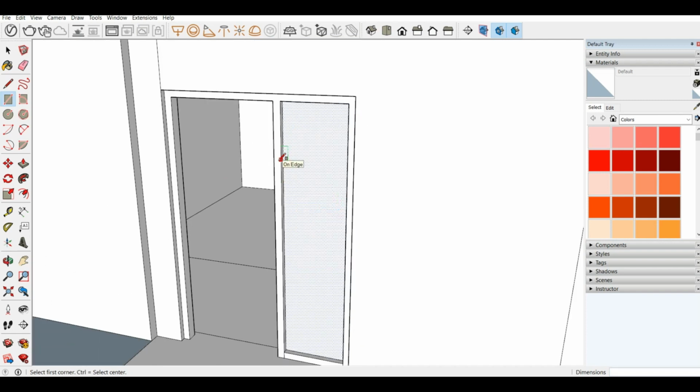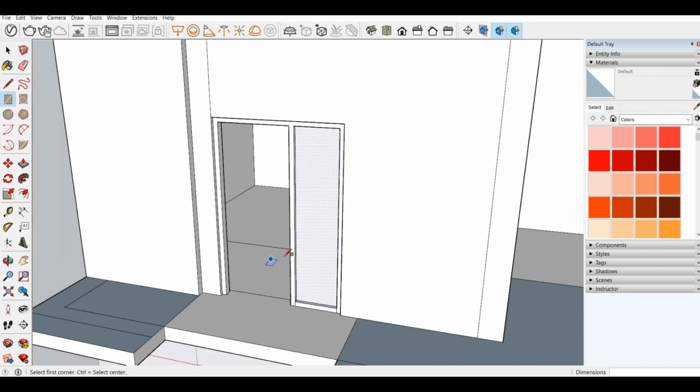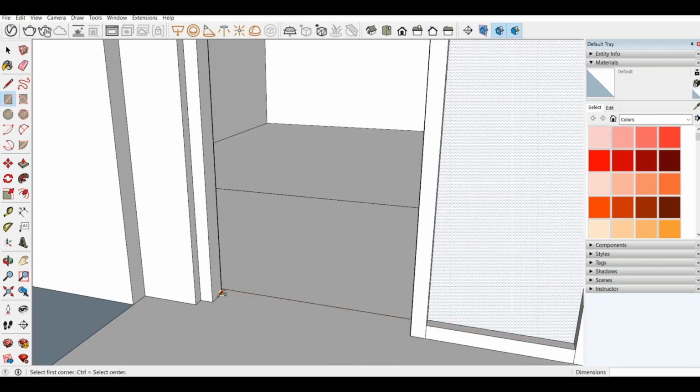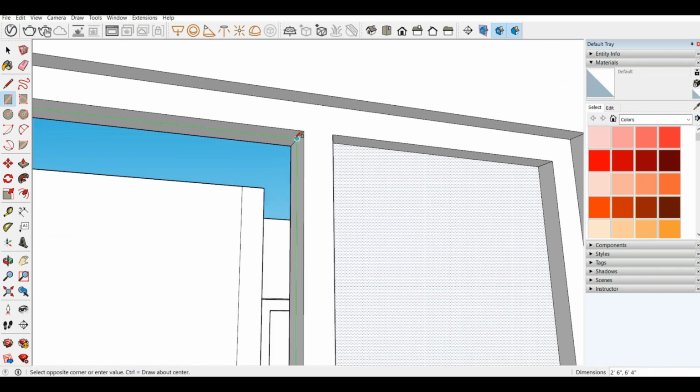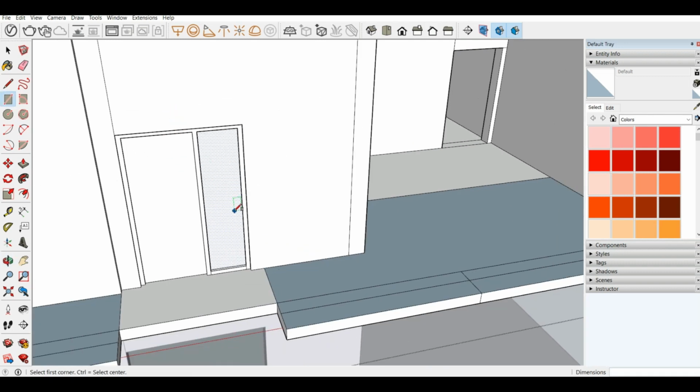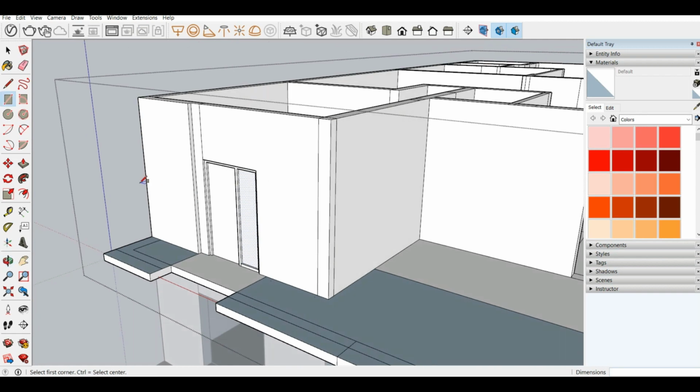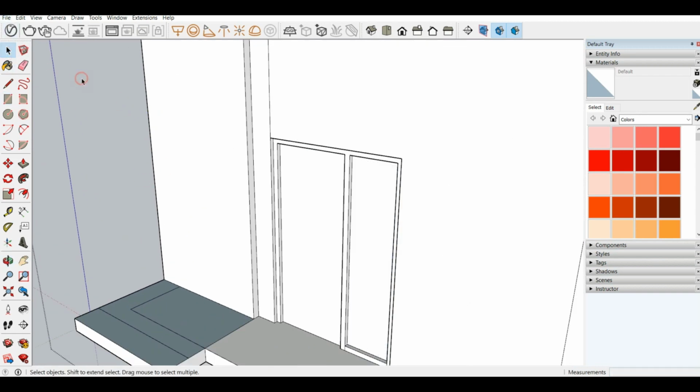So now you might be thinking why we do this reverse face thing. So the blue color you are seeing is probably the back face color, so the white is the front face color. So if you have a cube, all of the outside faces should be white and the inside faces should be blue. So we need the front face, of course, so that when we apply some materials later on using Vray, there isn't any problem during that process. So this is why we do reverse faces. So now we will give another rectangle for a glass here. Okay, this is already white.